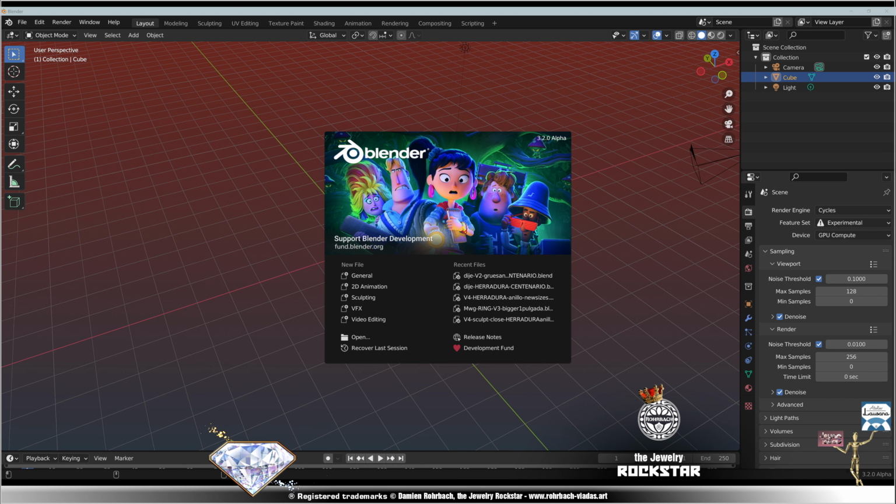All right, so now the gemstone needs a metal setting to put the stone in. So we're going to do a Shift D, click in place. Don't move it at all yet. Now we're going to scale it. Let's go to side view. Let's do an Alt Z to have a look at thicknesses. Okay, so it's going to be lower and higher, so we need S Z.